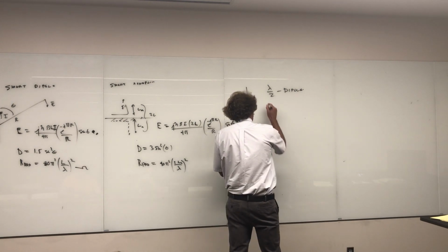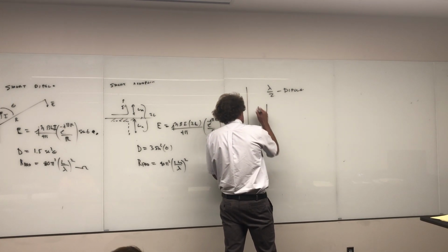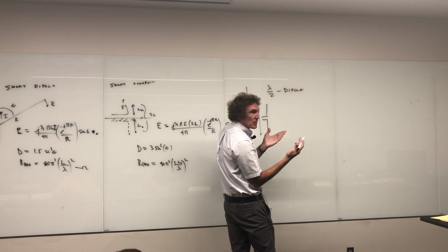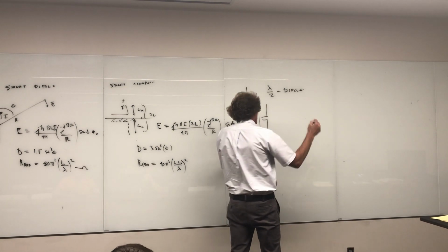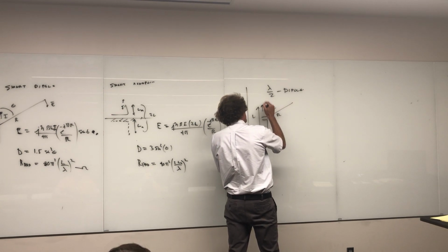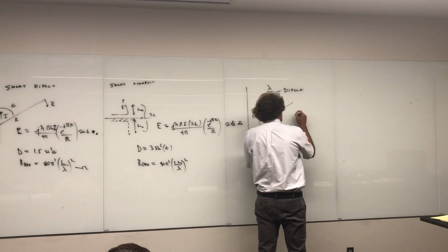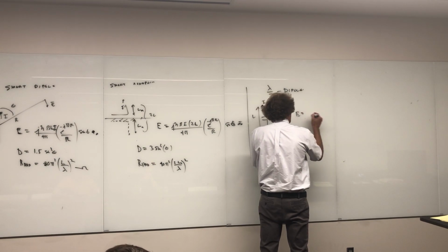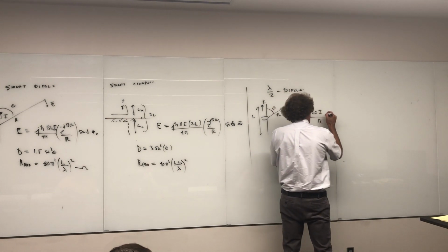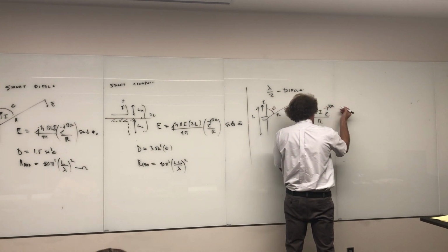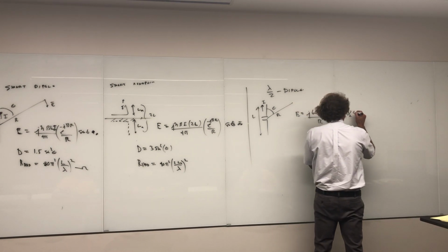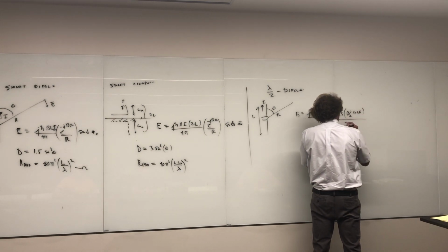Here, again, I'm going to be talking about something where I have a length L, and lambda is, or you could even put long dipole, but I'm going to put lambda over 2 dipole because this is the most common one. Now when I come out at distance r at an angle theta, I have a current I here. I know my E field for the half wave dipole would be equal to j times 60I over r times e to the minus j beta r, and then it's times that angular function, cosine of pi over 2 cosine of theta over the sine of theta.